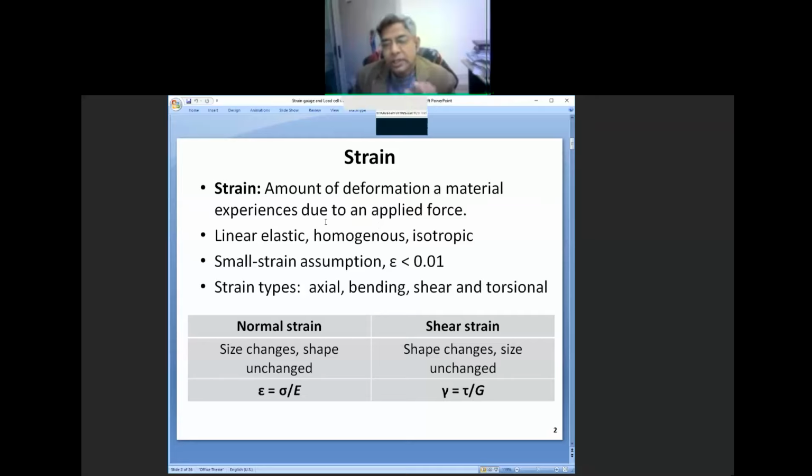Displacement is the relative motion of a point with respect to a reference axis. That's called displacement, displacement with respect to a fixed reference axis or origin. Deformation is basically relative displacement between the particles, between two particles that constitute deformation. So strain has both components. It has displacement and it also has deformation.